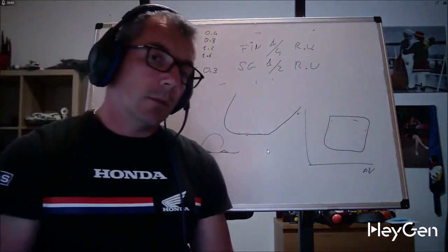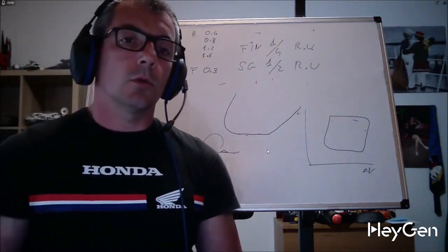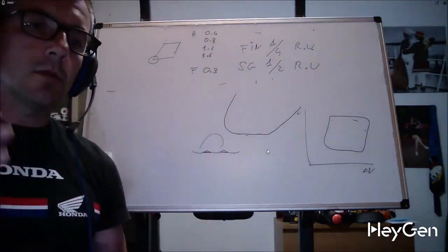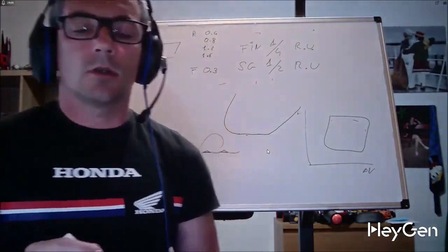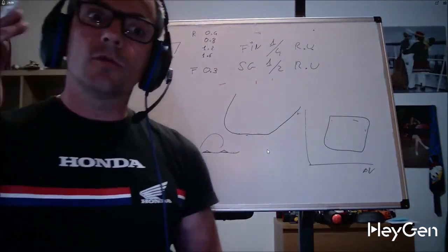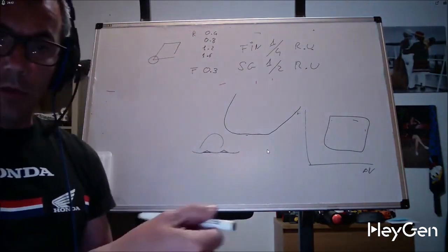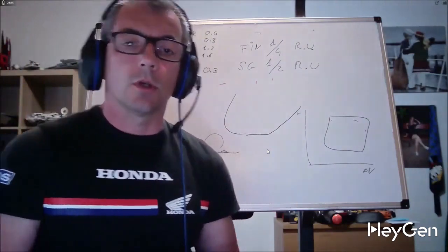I like to talk about them, I like to share them, I like not to rush, because I hope that those who listen to me will remember one day, ah damn, but I remember that if I work with the Viper, I could have vibrations, so maybe I won't use it on a boring tool, because boring tools are more susceptible, so tools for internal work are more affected by vibrations than external ones.